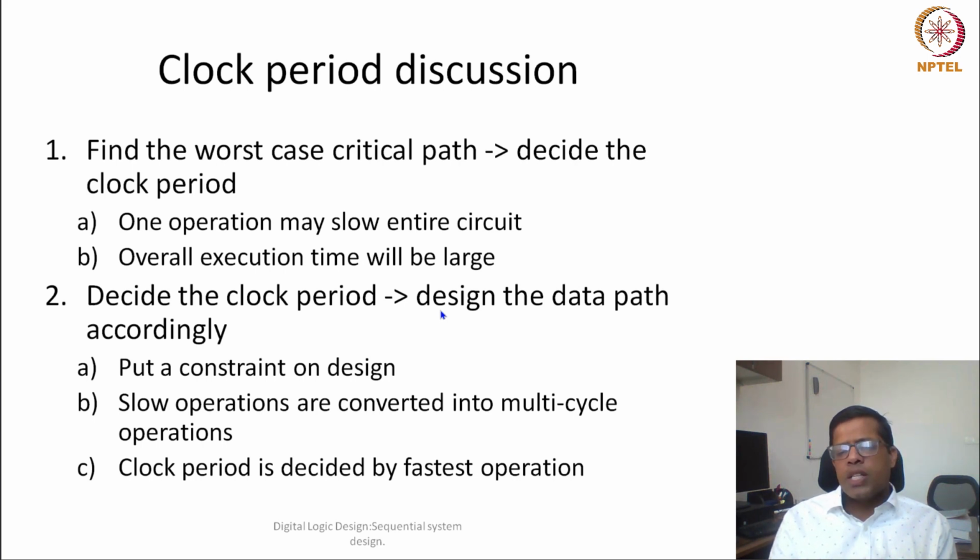In many of the cases, typically it's not a logical operation but an arithmetic operation which decides the clock period, and arithmetic operations which are quite common. For example, addition, subtraction, all of these operations can be done by an arithmetic logic unit, which can perform addition, subtraction, shifting, or sometimes multiplication is also included. So it is decided by whether they are the common operations or not.